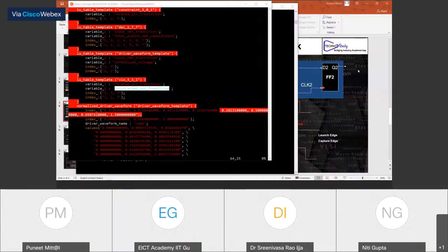Okay, so, doing STA on the synthesis netlist, does it include only cell delay or will it take the estimated net delay? Please explain. Harish, okay. So the answer is, if you provide the net delay, it will take the net delay. But there is another concept of wire load model, which I'm not going to discuss right now. If those models are there, then it will take the estimated net delay into consideration while calculating the timing or the delay value after synthesis.